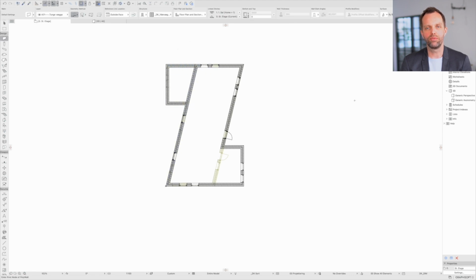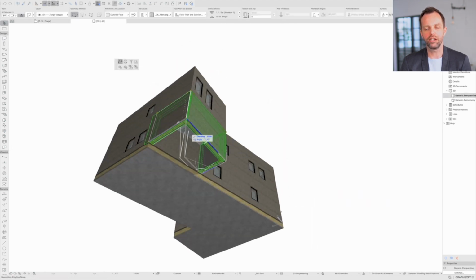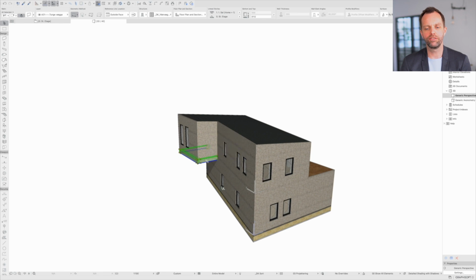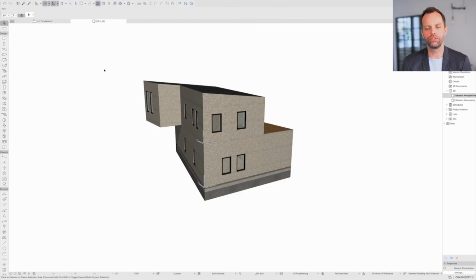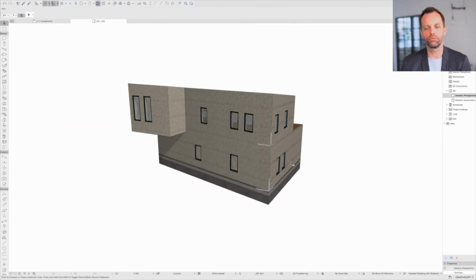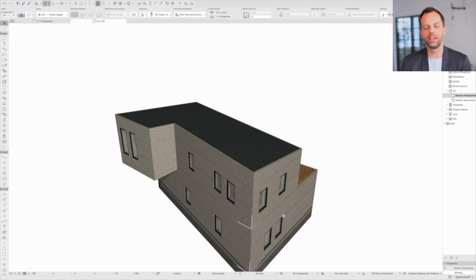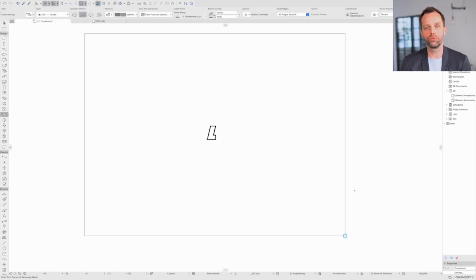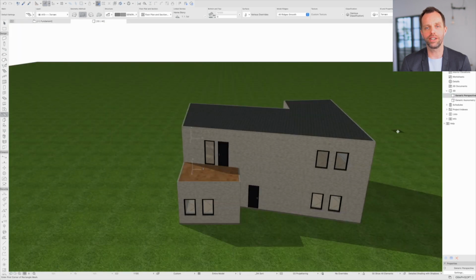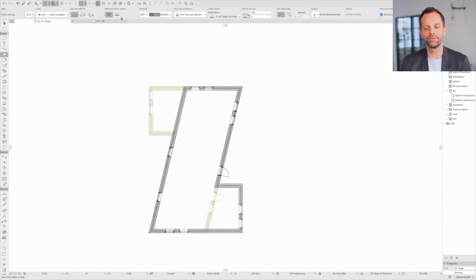And I want to have fairly precise LCA calculations, so I do a little bit of enhancements of the model. I also put a foundation on, and the reason is if you optimize the materials for your project for the LCA, the foundation will often be a larger part of the LCA since it's made of concrete.